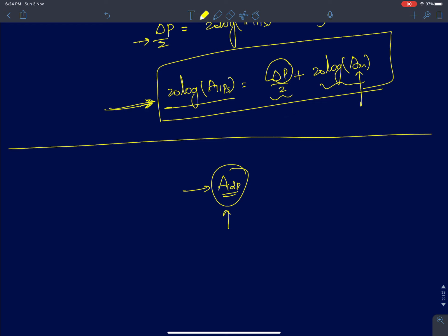But what happens if I have more than one interferer? Especially in a narrowband system, they can create havoc. They can actually create a new component at your desired signal. For that, we needed a metric, and we needed a new measure, and that we call AIIP3. Again, this can be expressed in volts or in dBm in power units.